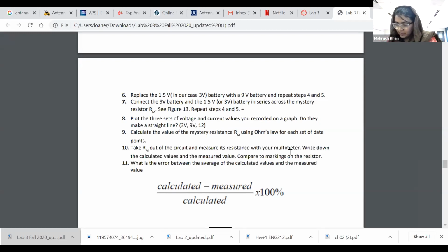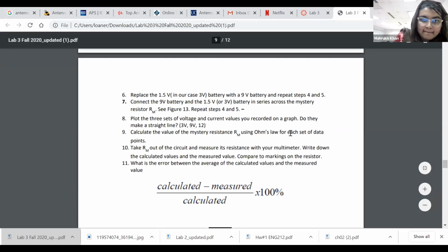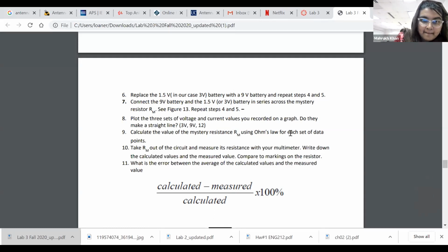So how can you do that? This circuit is not connected to anything and I want to measure its voltage. Oh, sorry, resistance. So I will move this to the resistance and I am doing it at 20K and just checking it. As a precaution, I'm taking the wires out. So I'm measuring this resistor, moving it to ohm meter, and 20K, I think.